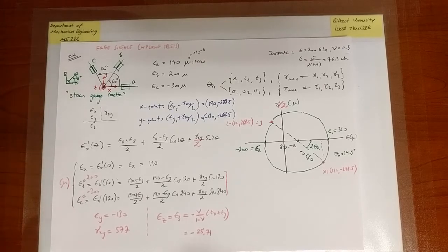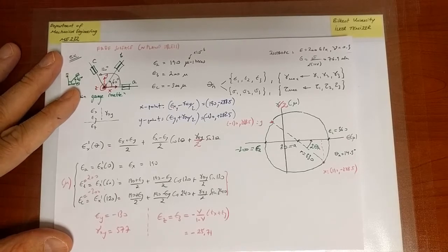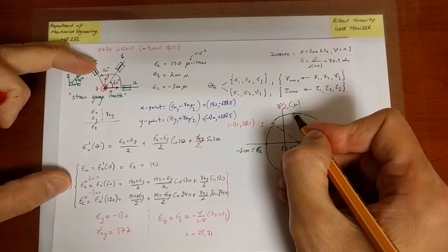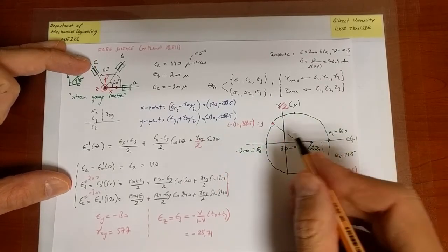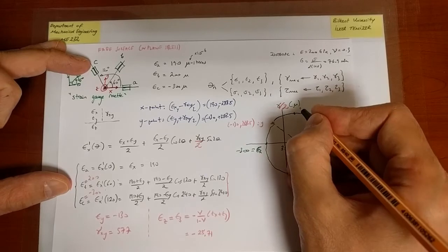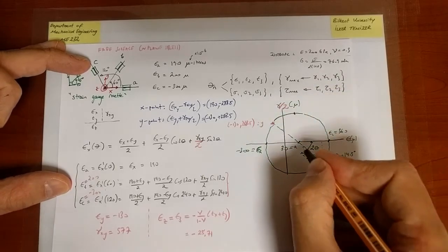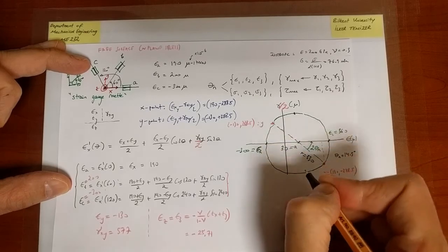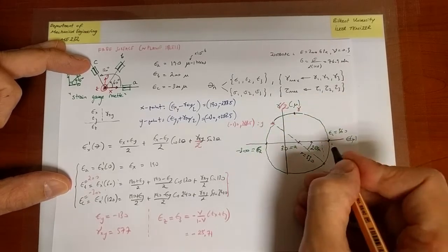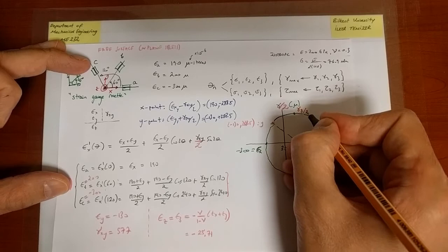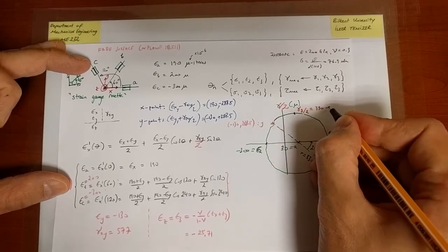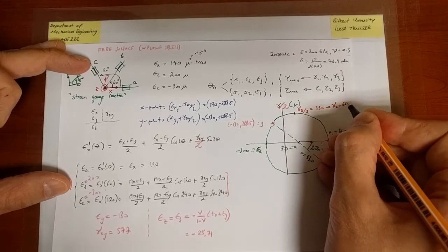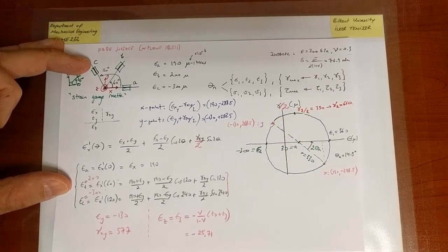So now of course, I can at this point immediately go and calculate the largest shear strain I obtain within the rotations that lie in the xy plane, or about the z-axis, and that would deliver me a value here that is equal to the radius 330 for gamma, so that's 1, 2, that would be gamma 3 half is equal to 330, or gamma 2 is 660 microstrain without explicitly saying so.